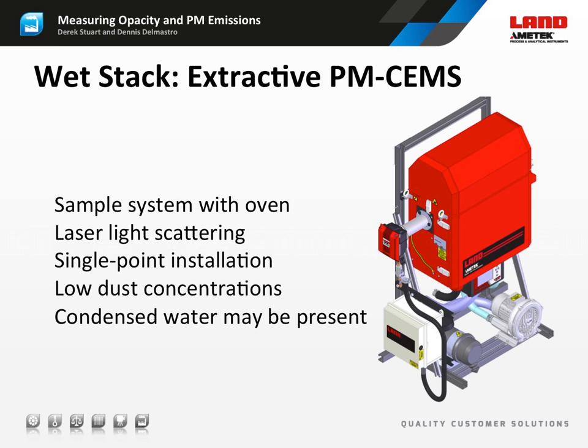There is a solution to measuring PM in wet stacks, but it is rather expensive. A heated extractive sample system takes some of the flue gases to an oven. Provided the residence time in the oven is long enough, the water drops evaporate and the hot, dry sample can be measured using a standard forward scattering sensor. Careful design is needed to ensure the PM entering and leaving the oven remains representative of the material in the stack. Unfortunately, all of the additional hardware increases the price of the PM-CEMS by a factor of 4 or so relative to an in-situ system.